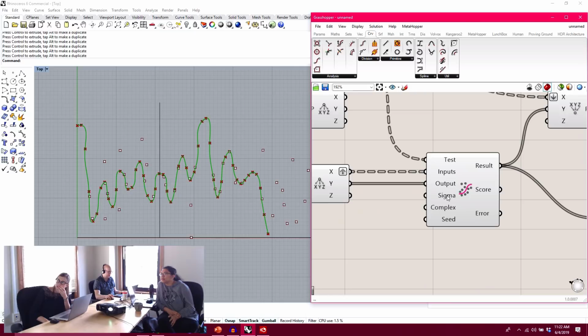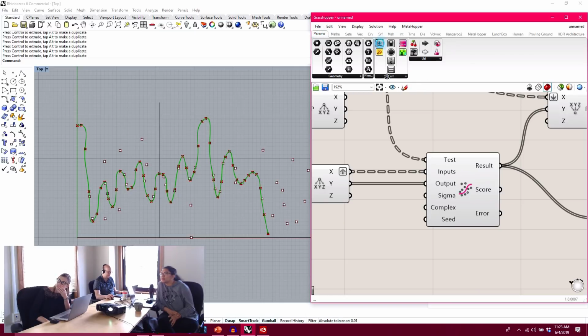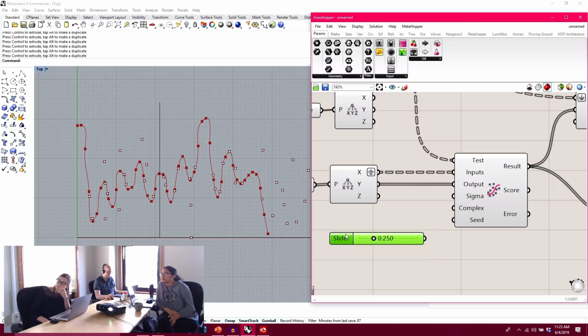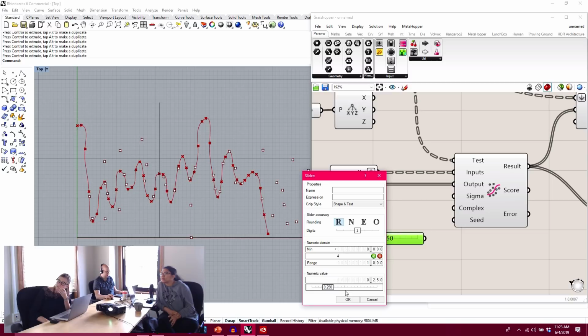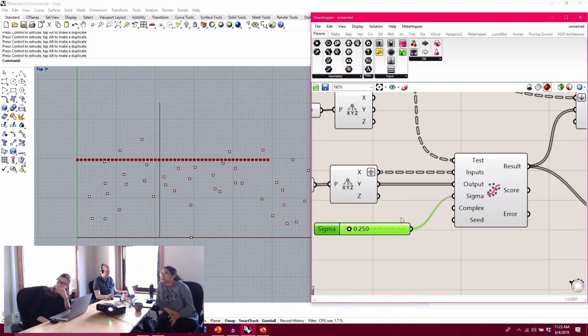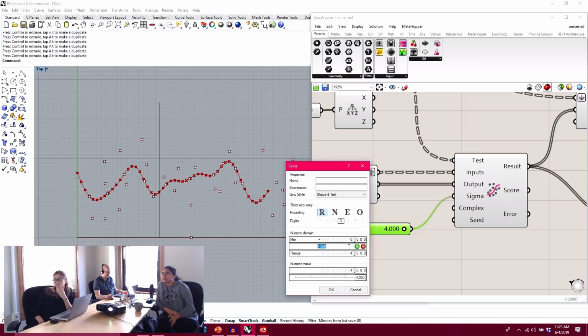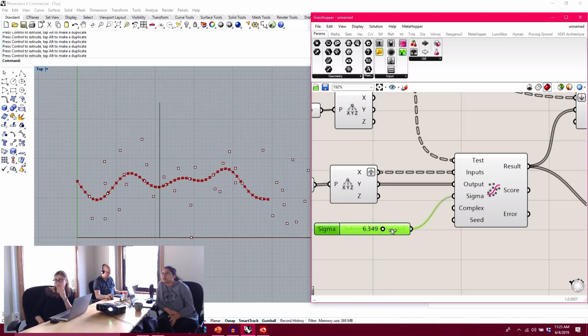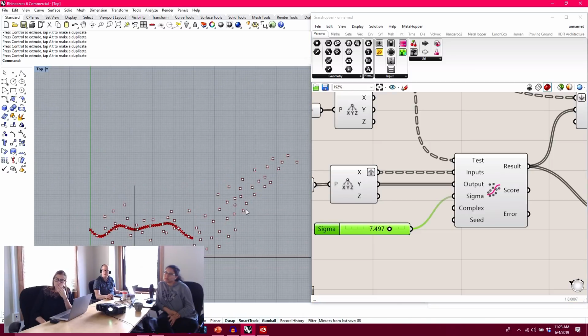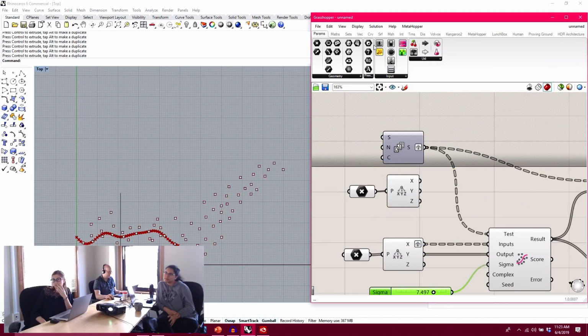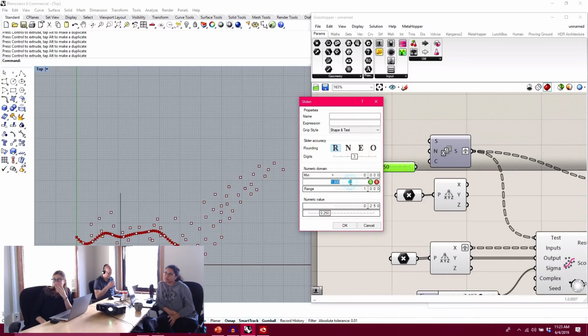This is where some of these tools down here for calibrating the fit curve can become really useful. So I'm going to jump over here, and we're going to adjust our constraints of this curve. By calibrating this even further, maybe something like 10, we can start to get some kind of predictive curve that attempts to reconcile or rationalize this overall collection of points. I can continue to extend this if I would like to. Right now this count is at 50? I'll take this to 200 as my count.